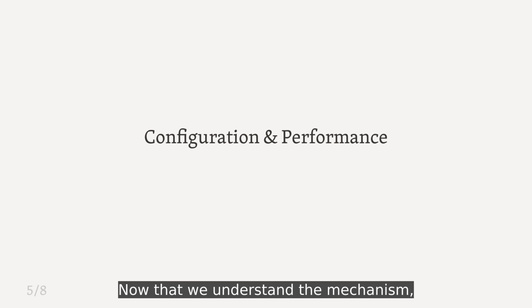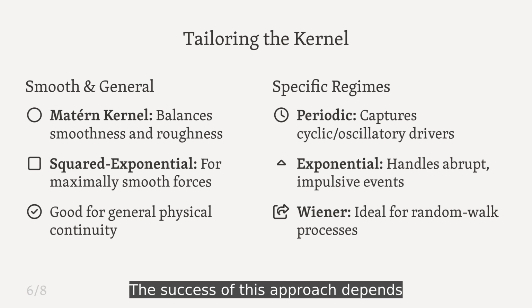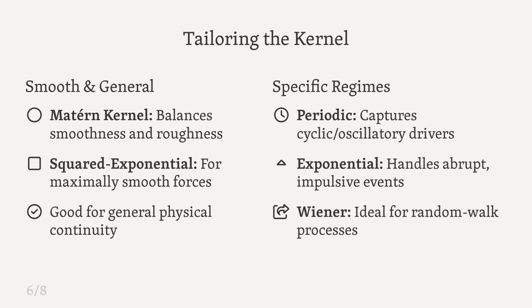Now that we understand the mechanism, let's look at how we configure these models and how well they actually perform. The success of this approach depends heavily on choosing the right kernel, which describes how the force behaves over time. We use Matern kernels for standard physical forces that change smoothly, but we can switch to periodic kernels to capture vibrations in rotating machinery, or exponential kernels to detect sudden, abrupt impacts.